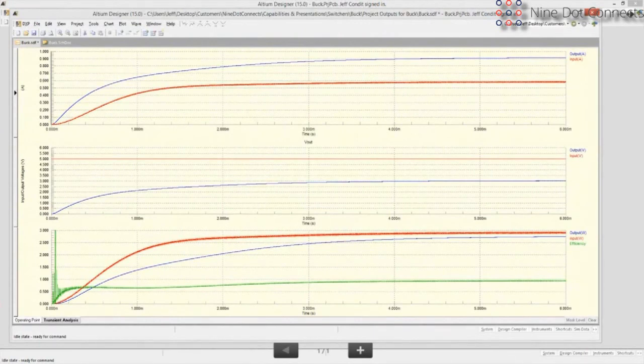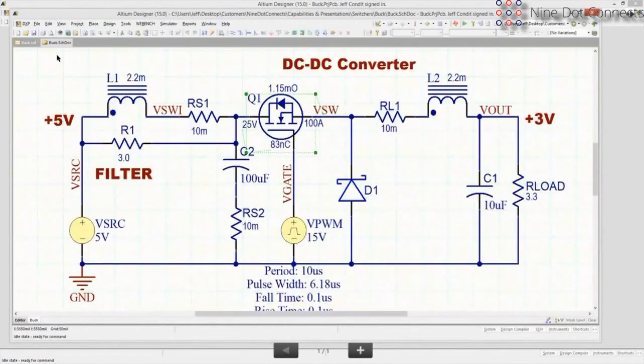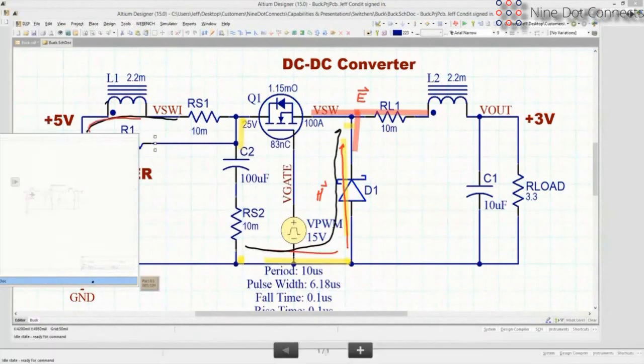Okay, that's a very, very good question. Let's talk about that. Let's go back to the schematic. When we talk about the current loop, there is a net DC power flow through the system. So we actually have power coming out and flowing in a DC way through into the output. When we talk about the loop, we're only talking about the AC component, or the switching component. It's not really true alternating current as in sinusoidal.